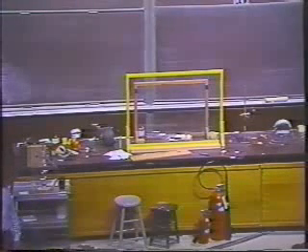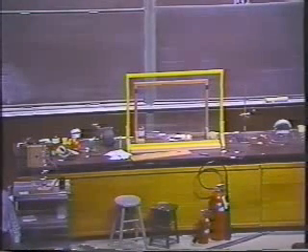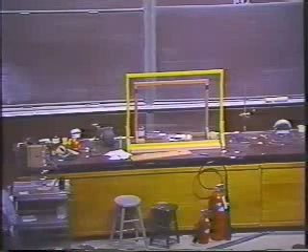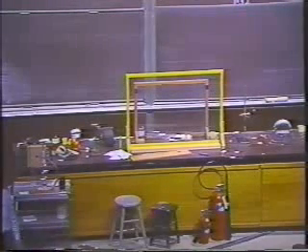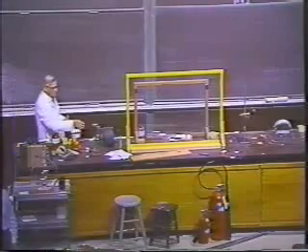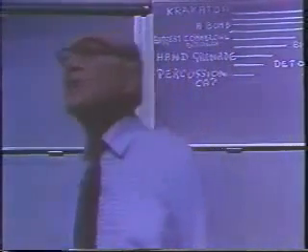And they have at one end a heating tube which can raise the temperature by means of an electric current. This, of course, vastly increases the pressure, and the bursting cap of thinner metal at one end of the tube gives way, and the carbon dioxide comes out of the holes at the end with explosive force and acts as a very good explosive on, for example, a seam of coal. No shattering effect, and of course carbon dioxide is a fire extinguisher.